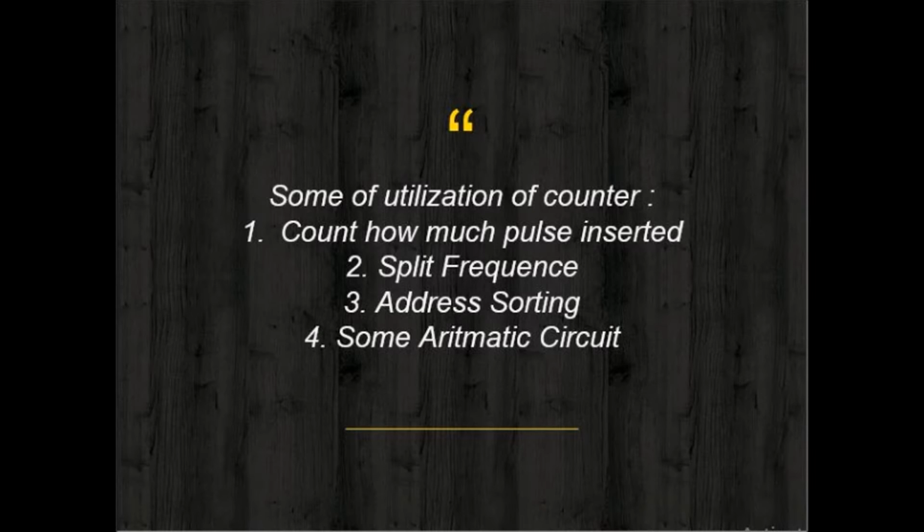Here are some utilizations of counters. First, we can use it to count how many pulses are inserted. Second, we can use it as a frequency divider. The third one is address sorting. And the last is some arithmetic circuits.